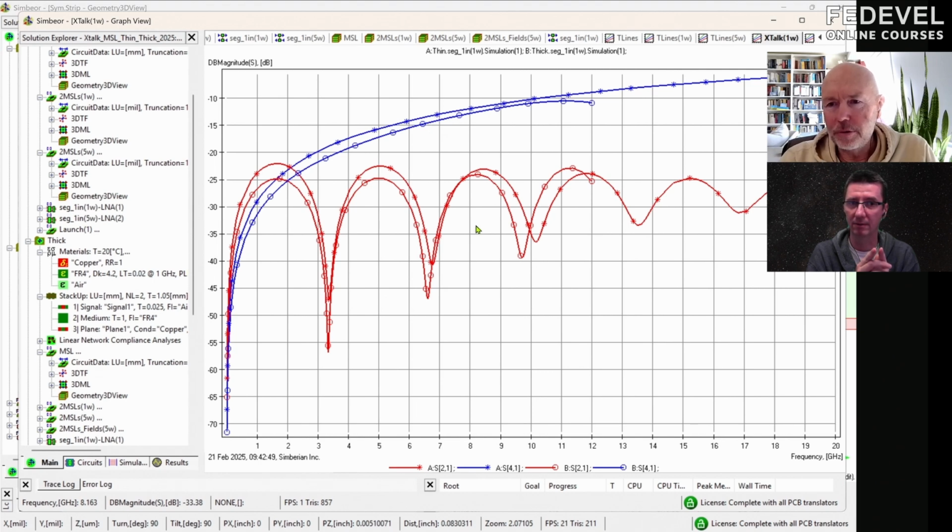2 millimeters. No, for the small one. Thin is 0.1 millimeter, or 4 mils. So 4 mil, and we are still getting kind of the same crosstalk, but the tracks are much closer. And this crosstalk is wider still tracks. Yeah, this crosstalk is still quite high.